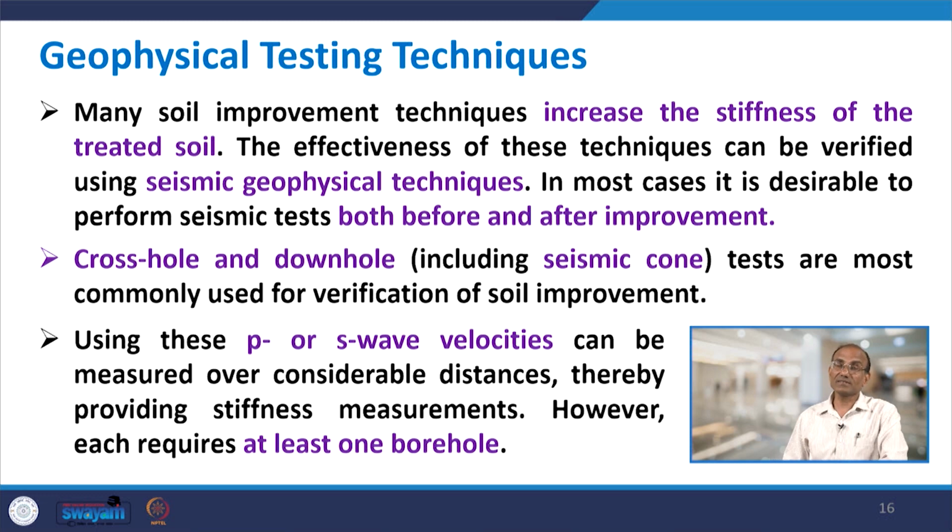Now, another category, the third category: we discussed laboratory tests, then in situ tests, and the third one is called geophysical testing techniques, where geophysical equipment and methods are used. And what are geophysical methods? We already discussed them in much detail when we discussed dynamic soil properties. Many soil improvement techniques increase the stiffness of the treated soil. The effectiveness of these techniques can be verified using seismic geophysical techniques. In most cases, it is desirable to perform seismic tests both before and after improvement.